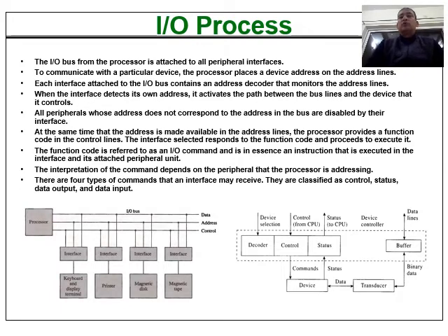When the CPU wants to communicate with a particular device, it takes the address of that device and puts that address on the address lines. There may be a number of input-output devices connected to the I/O bus, and each one is identified with the help of a device address. Let us assume that the keyboard is device number 1, the mouse is device number 2, the touchpad is device number 3, and so on.